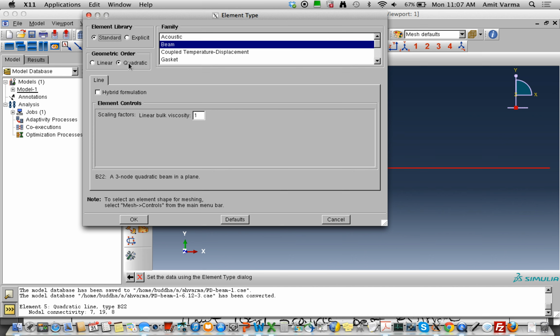I'm using more than one element, am I not, along the length? If I was using just one finite element, I would need to use a Hermitian polynomial, and I was trying to do an elastic analysis. It would give me the most accurate answer, because the behavior follows the Hermitian polynomial. That's x cubed divided by L cubed. What I mean by that is that the formulation of your finite element, if it is identical to the formulation of the displacement that you get at the end of the analysis, then your answers will be done in one finite element. You will need only one, if your shape function is the same as the displacement function would be in the mechanics space solution. Do you know what I'm saying?